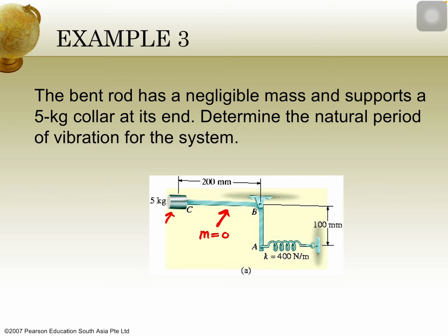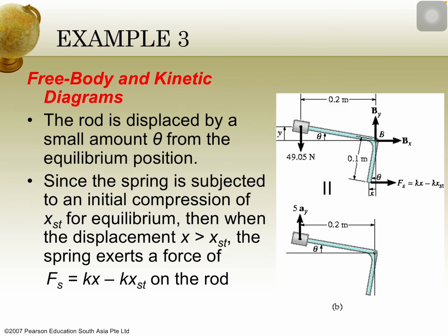So you need to consider all parameters given here. Alright. Again, the first thing you need to do is draw the diagrams: the free body diagram and the kinetic diagram. The free body diagram is right here, and the kinetic diagram is right here. And we need to draw the free body diagram with an angle.